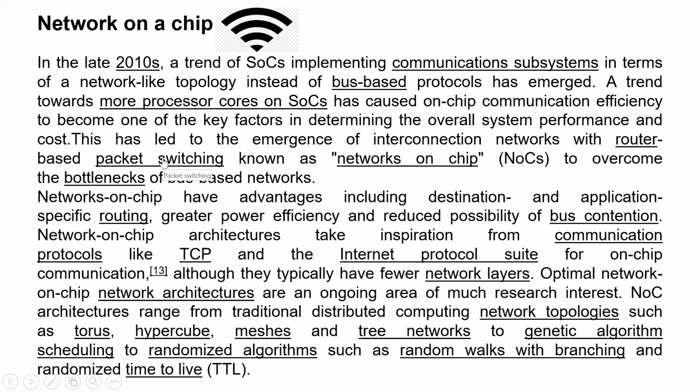It provides power efficiency and reduces bus contention. Bus contention means bottleneck of the bus. This network on chip has its own architecture, built from the standard TCP/IP protocol suite. Not all the layers of TCP/IP are there in NoC, but fewer layers are used, and these fewer layers operate in line with the TCP/IP protocol.